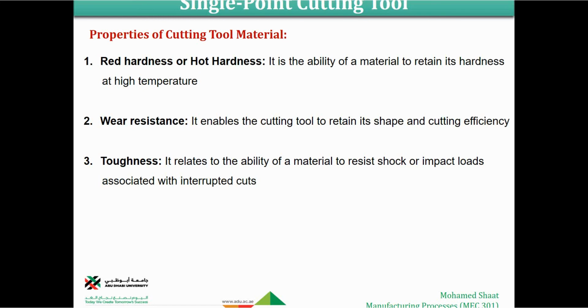the machining process. But in addition, there is an essential thing that this material must include: the capability to withstand the high temperature or the high heat that is generated during the machining operation. We said that in machining there is a direct contact between the tool and the workpiece, and we have two or three main sources of generating heat.